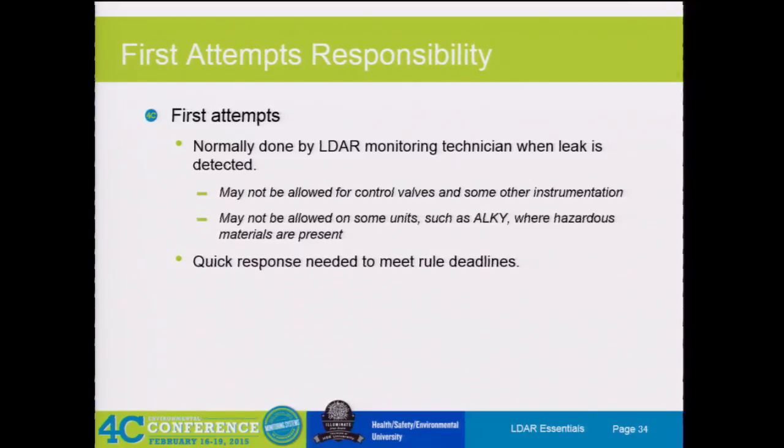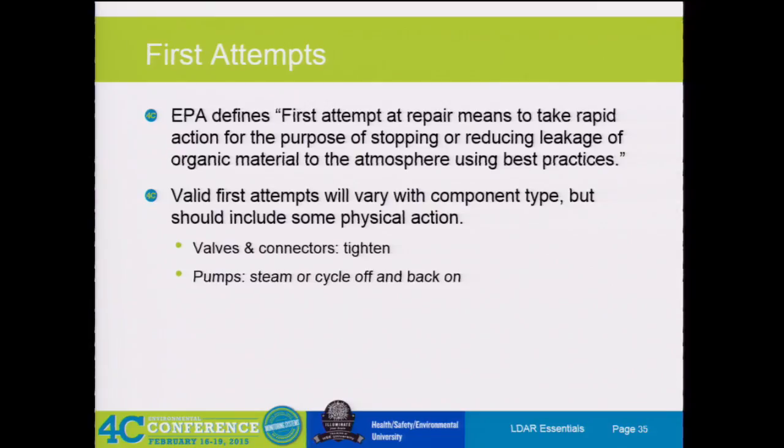With maintenance, you only have one valve on the discharge and a service block. You have a low point open. Would that be considered an open-ended line? No, if it's purged, you're good. And if it's a maintenance activity, you can have an open end, and it's also considered purged. If it's open to atmosphere and they're doing maintenance on it, you don't have to monitor it.